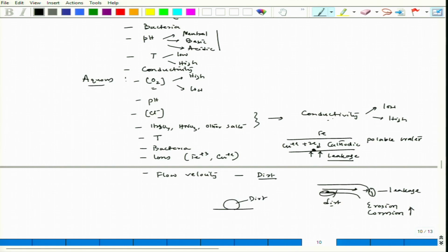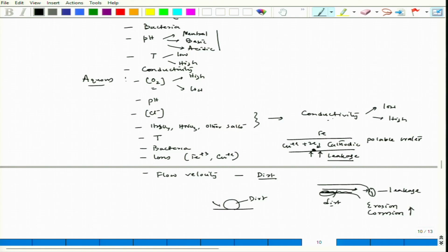Now, interestingly, when heavy dirt is present, it falls down and deposits at the bottom, and it reduces the orifice. That means the flow of water, or the aqueous medium, is hindered. That would lead to another problem, turbulence. Turbulence is another issue we will talk about later, but let us say the dirt is settled at the bottom. So, you are actually creating a crevice.